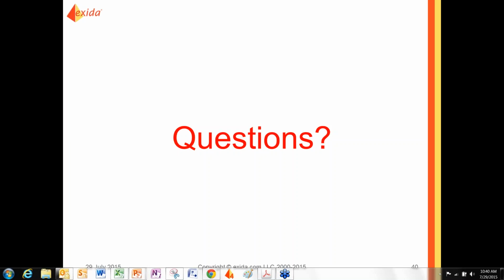Here's a question: how can you integrate the SIL study within the HAZOP study in a fast way? You need calculations that can't be made while the HAZOP study is working. How can that be possible? I think the question is basically, we're doing our HAZOPs, we're trying to determine if we have enough safeguards, but we haven't designed the SIFs, so we don't know what the number is.